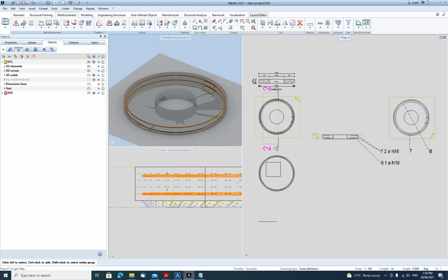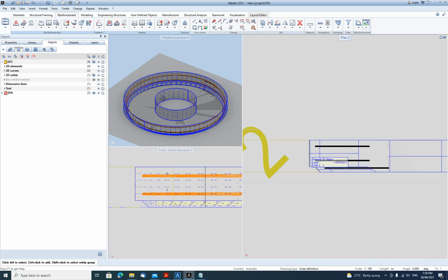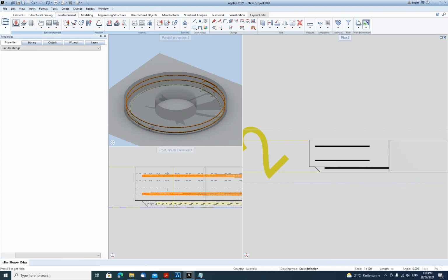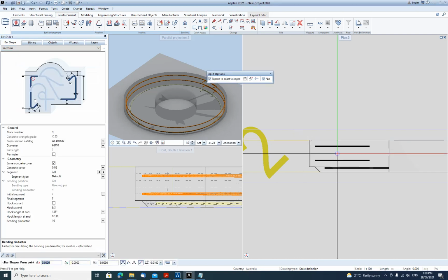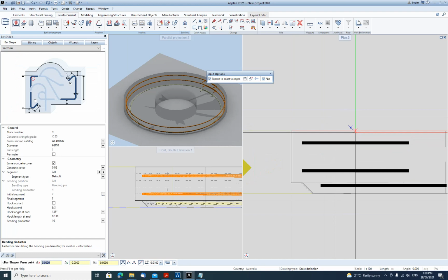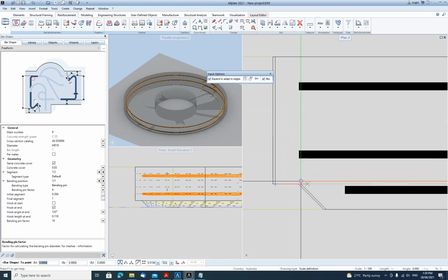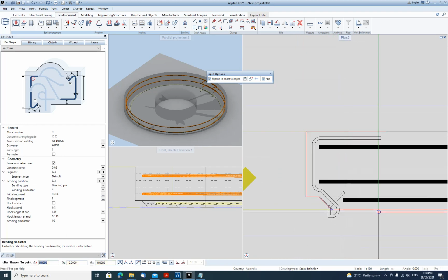For the next step, I'll create a freeform stirrup which will enclose the edges. I will return to my reinforcement command and choose Freeform. Freeform is a very adaptable and modifiable command, so I can start basically wherever I want and continue down the way with my placement.